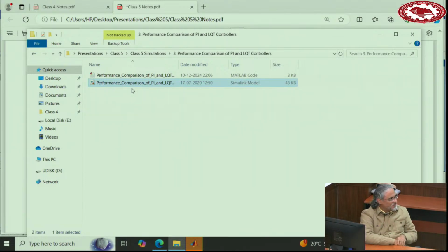So here I chose 1 millisecond for the low pass filter. Because we just calculated that if you have 1 millisecond, the transient time of the system, we chose the poles about 1 millisecond, and we said that it cannot limit the current. So if you add that filter, it will help. You don't want to choose 10 milliseconds, right? Or even a fraction of a millisecond. A fraction of a millisecond for current limiting is good, but it will have the problem of bringing the noise of the grid to the feedback loop. But if you mean delay in the feedback loop, no. Here, the delay of the low pass filter does not go into the feedback loop.